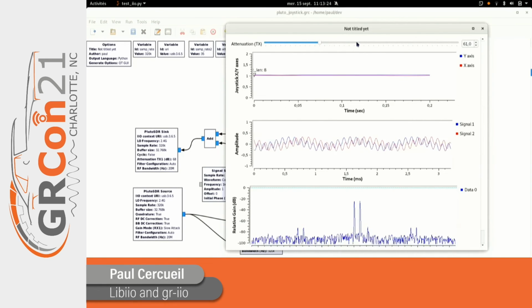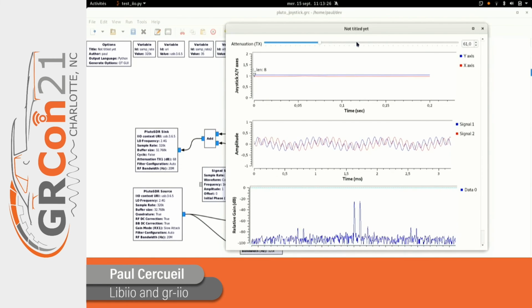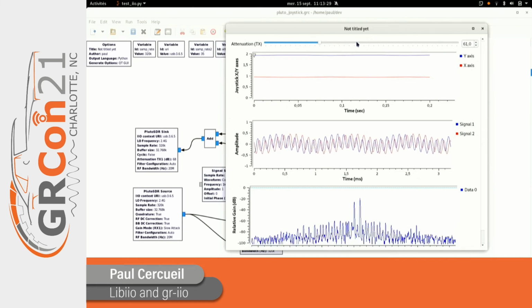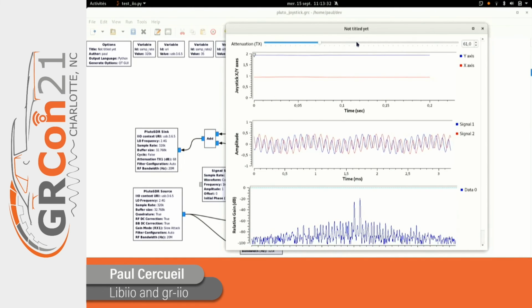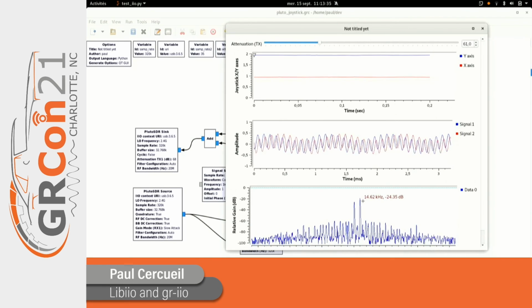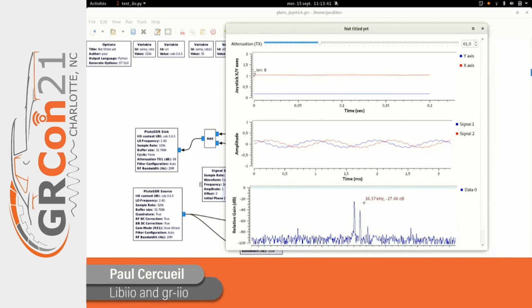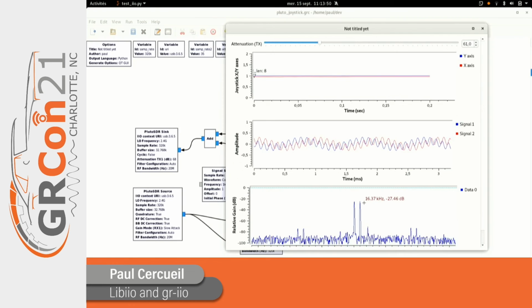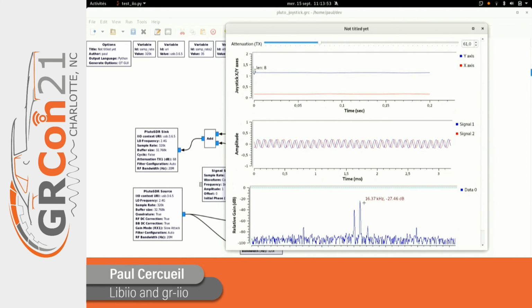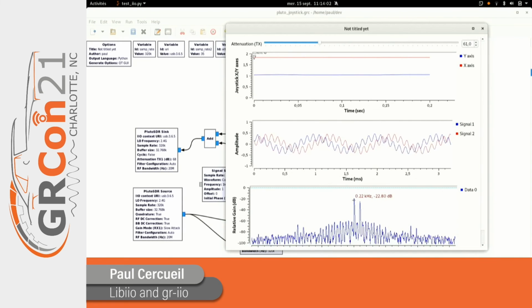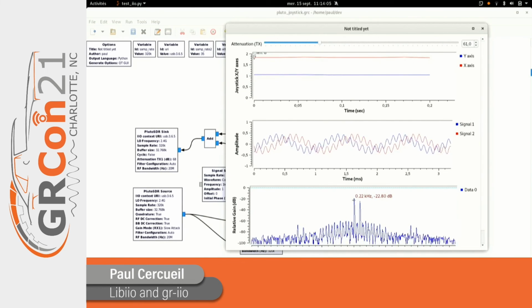And now, as you can see, if I raise the y-axis, so raise the joystick, the 10 kilohertz sine wave increased in amplitude. The value in dB is much higher. And if I lower it, then it looks like we almost only have the 1 kilohertz sine wave. Then if I move the X joystick, you can see on one side I can really reduce the 1 kilohertz sine wave, and on the other side I can just make it stronger.